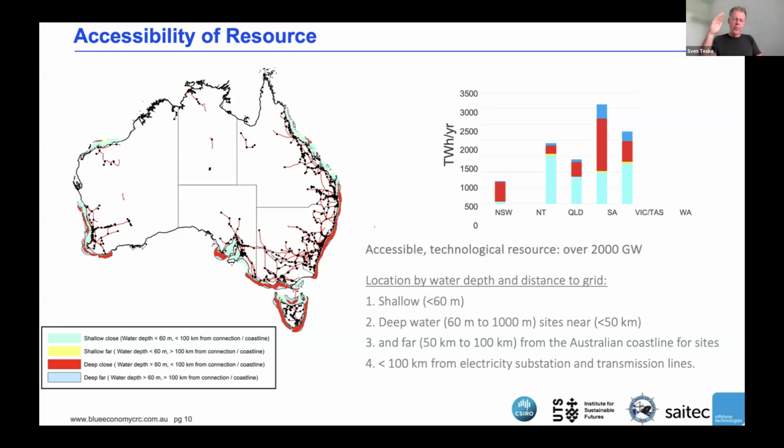So therefore, if you really scale down and subtract all the barriers, you see that the actual places where you could start with offshore wind are quite limited, and they are around the existing fossil fuel industries, as there is strong infrastructure. In terms of the grid, where the coal power plants are, for example, about 150 kilometers north of Sydney in the Newcastle area in Hunter Valley. Hunter Valley is basically one large area for the coal industry. There are very large substations very close to the shoreline, which means you could actually connect the offshore wind farms from the sea straight to the existing interconnector and substations which were built for coal.